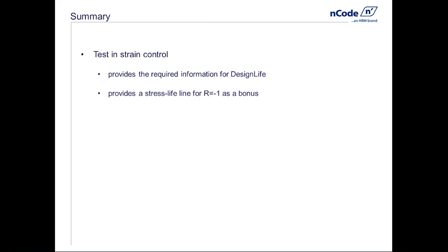Another word of warning at this point: stress life people talk in terms of cycles, strain life people talk in terms of reversals. And the reason for that is because of the theory, there's no difference, you just divide the number of reversals by 2 and you've got cycles.